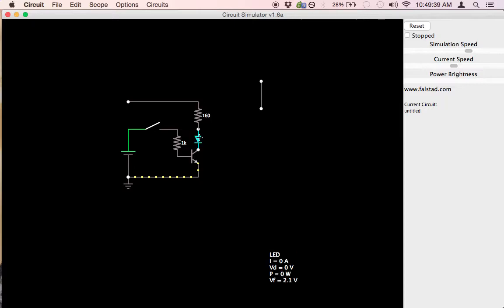We're going to connect the positive terminal to the positive of our supply. Here we go. Now, as you can see by the green color, there is a positive voltage available to the LED. But where does that positive voltage stop? In the transistor. The transistor is off right now. No current is allowed to flow into the collector and out of the emitter until we turn the transistor on. There again, we do that by simply applying a small amount of current to the base by closing the switch. And now you can see the circuit in action.